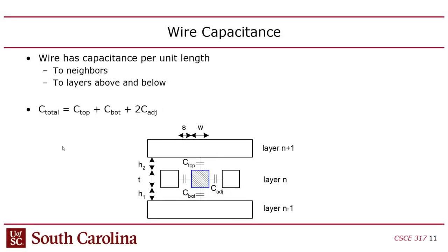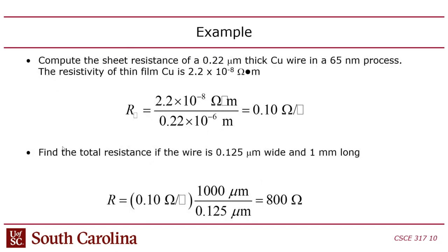You'll see on the quiz there are similar questions. So that's how you calculate the resistance. Basically, you start with the material that you make the wire out of, which gives you the resistivity, and then you get a thickness and then a width and a height.